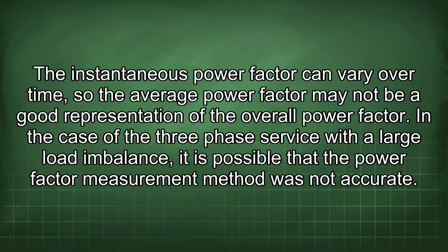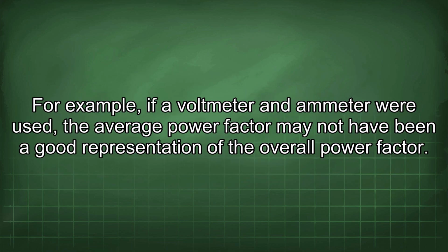In the case of the three-phase service with a large load imbalance, it is possible that the power factor measurement method was not accurate. For example, if a voltmeter and ammeter were used, the average power factor may not have been a good representation of the overall power factor.